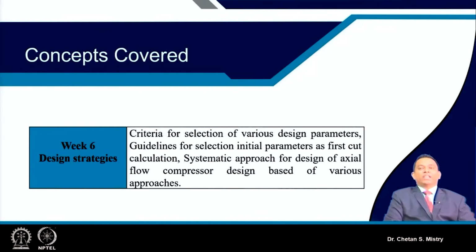We realized that if we are planning to design an axial flow compressor for aero engines, it needs special attention. That starts with basic cycle analysis, the gas turbine thermodynamic cycle analysis, based on which we calculate initial parameters such as mass flow rate, speed, efficiency, pressure ratio and temperatures. Later, based on our expectation, we plan to distribute the overall pressure ratio between the LP compressor and the HP compressor.